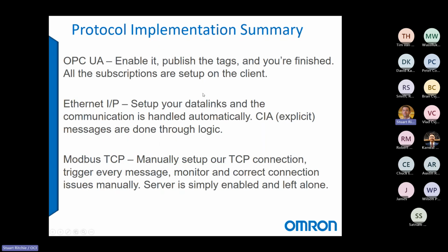Okay, so kind of to wrap up what we covered today, OPC-UA, if you use SCADA, you probably support it. Very simple, enable it, publish your tags, and you're finished. The vast majority of the work is done on the client end, but it's a very convenient way. With the latest firmware on our PLCs, not even the latest, I think this is something we implemented a year or two ago, but we'll actually support structures over OPC-UA now. So you can even use structures on OPC-UA now. We've kept pretty up to speed with it.